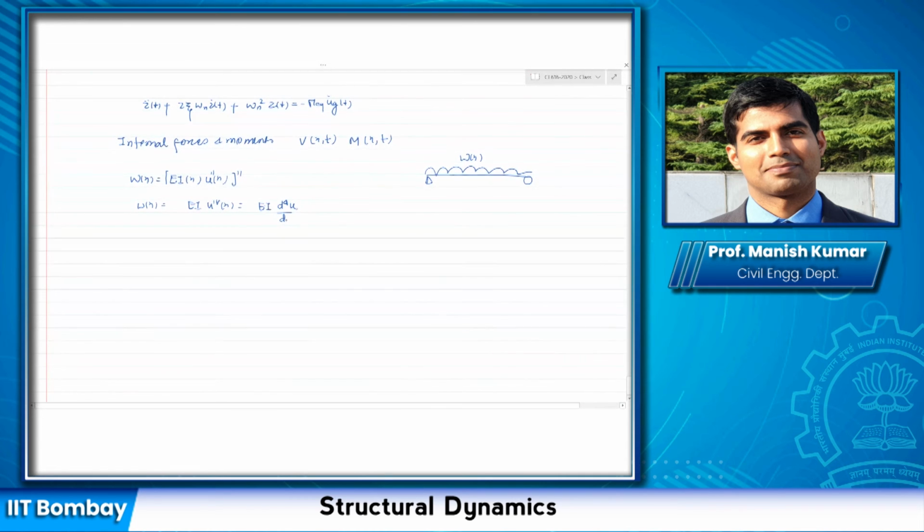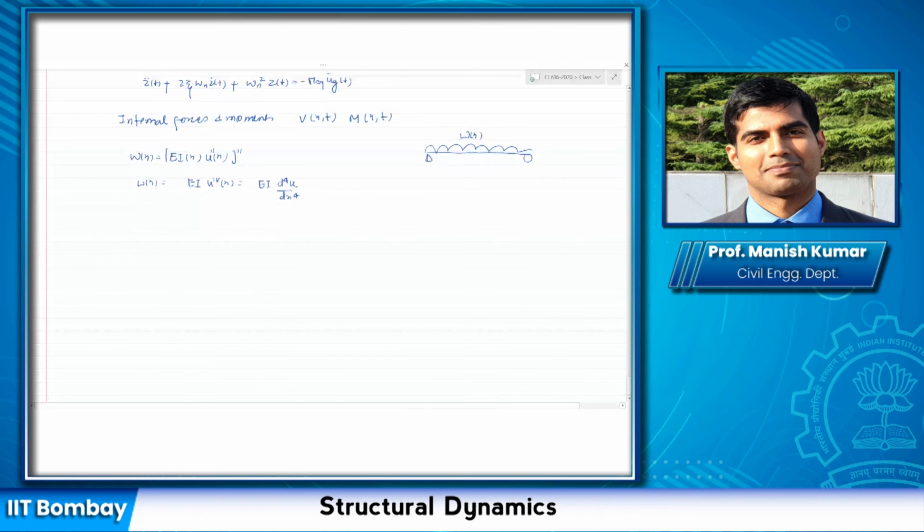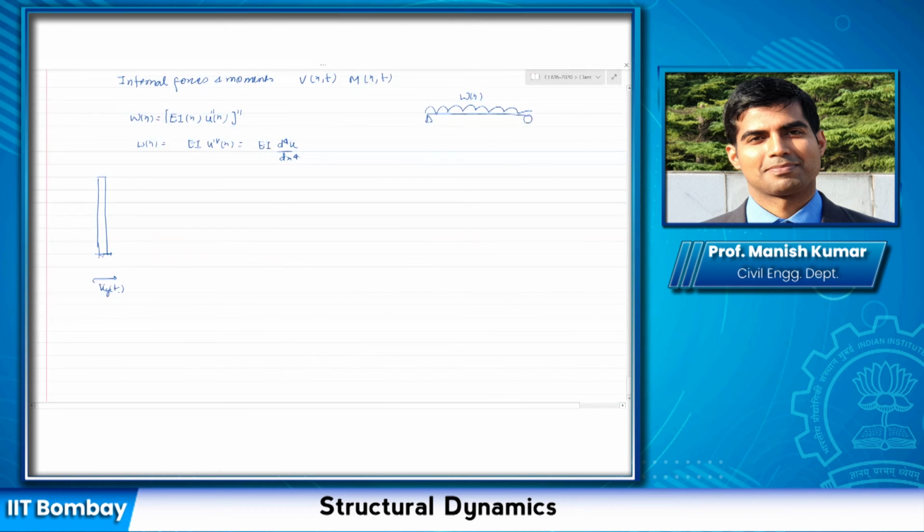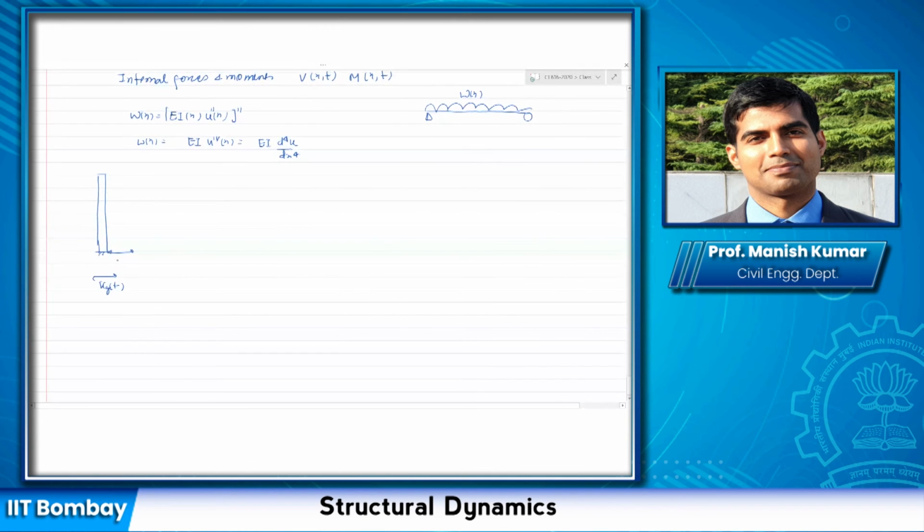This was the equation you might have seen, and we are going to employ the same thing. So for a case of an earthquake excitation, where the ground displacement is u_g(t), and we formed something like this, and we used the virtual displacement to derive the expression. This we considered as U, this as del U. At the end, we normalized with respect to end displacement, so we said that this would be Z and del Z.